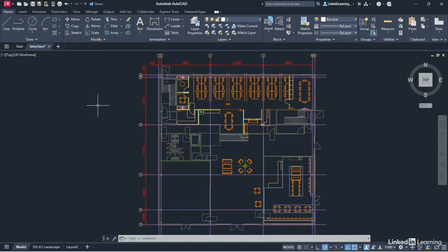Now, I mentioned this a little bit in the previous video when we were talking about dynamic input. Dynamic input is always switched on in a default installation of AutoCAD, but you can't control the settings because the dynamic input icon is not switched on the status bar, bottom right of your AutoCAD screen. So how can you switch settings on and off on your status bar and use it to your advantage in AutoCAD? Very quick and easy.